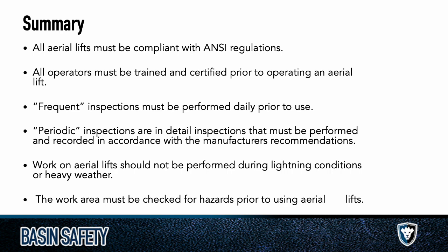All operators must be trained and certified prior to operating an aerial lift. Frequent inspections must be performed daily prior to use, and then periodic inspections are typically going to be your annual ones, and those do need to be documented and maintained for 5 years.